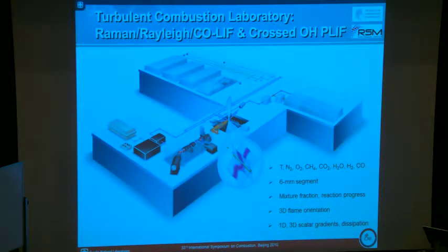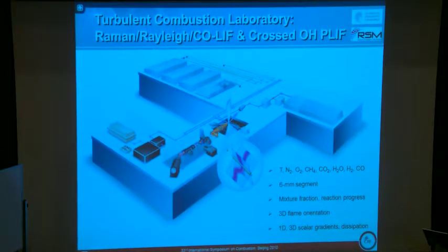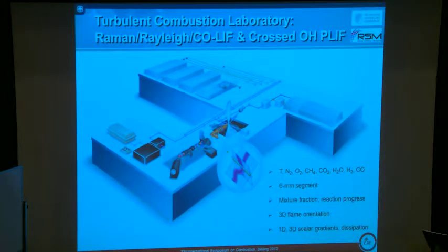Now we come to the question whether the system is mobile or not. This is the Sandia version, having the set of lasers which are fired sequentially, 3 delay lines, where I have shown how one is constructed. This burst is sent through the region of interest. You have the 1D line. We forget these sheets here that are to look for the orientation, how the line is intersecting the flame front, because that's of course important. Yeah, you will have a flame structure, different, identical flame like this or like this. That's why that is done or combined here with crossed sheets.